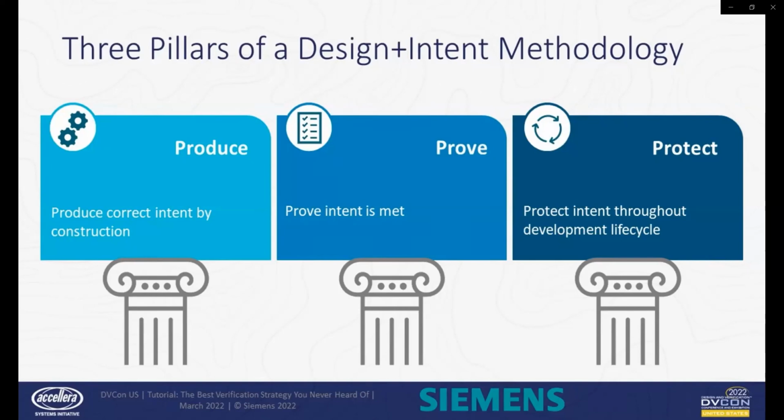A development lifecycle that incorporates design plus intent does not make verification any less important than it has been. In fact, the goal of the design plus intent process is to improve verification efficiency by decreasing bug density, which impacts downstream processes and consequently reduces cost. While a design plus intent bug prevention strategy encompasses all aspects of IC design, there are design solutions that exist today with the principal focus on improving RTL quality, such as static analysis.